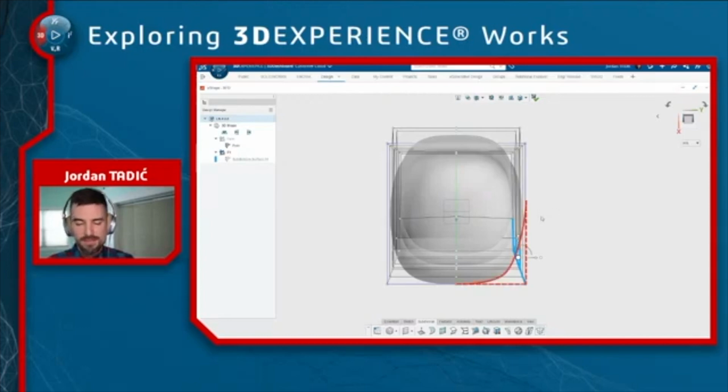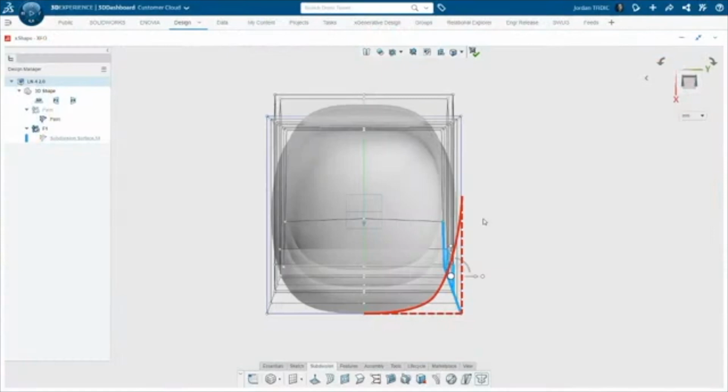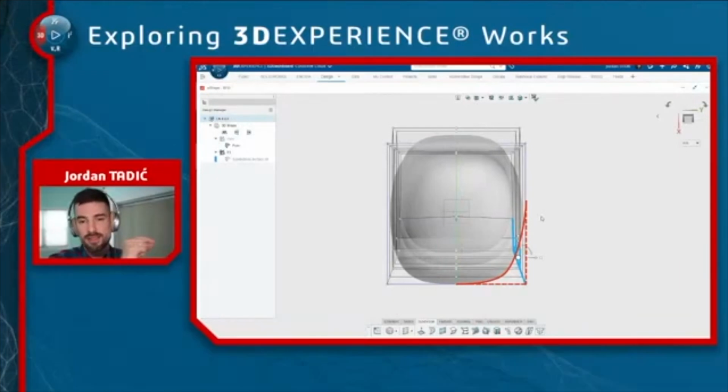Now, if you've ever sketched a spline in SolidWorks, you'll understand this pretty well, because the new style spline that we added a handful of years ago is the absolute easiest and most efficient and highest quality way to sketch a spline in SolidWorks, because you're doing it with construction lines and it's best fitting a spline through those. Makes it easy to parametrically define with dimensions and sketch relations.